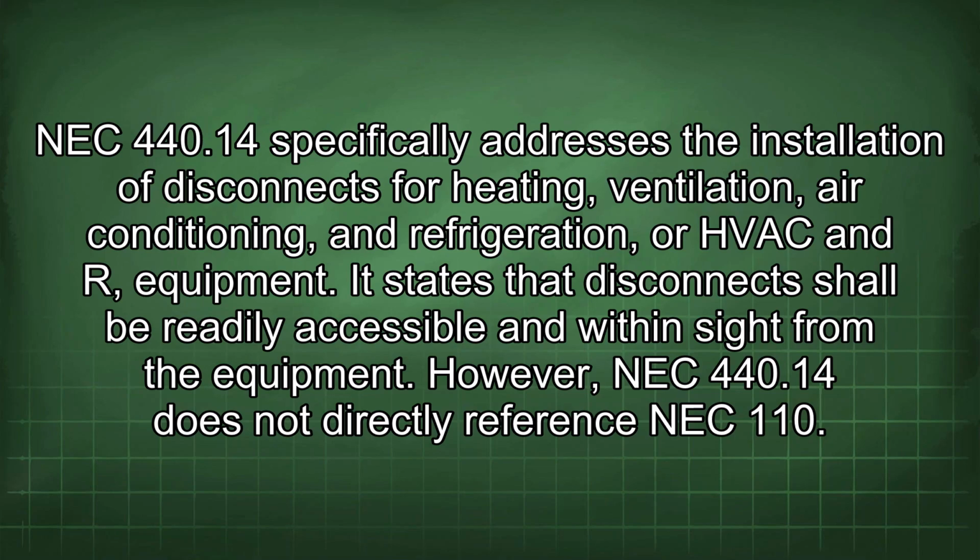NEC 440.14 specifically addresses the installation of disconnects for heating, ventilation, air conditioning, and refrigeration, or HVAC and R, equipment. It states that disconnects shall be readily accessible and within sight from the equipment. However, NEC 440.14 does not directly reference NEC 110.